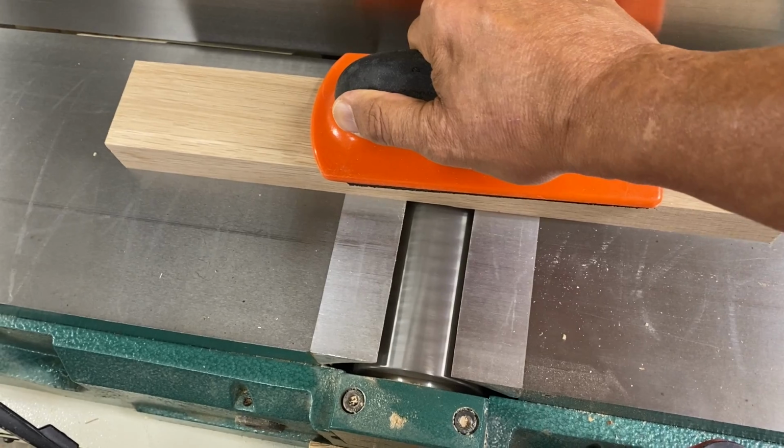I think what happens is the leading edge of the board develops a tiny bit of tear out as it passes over the cutter head, and that catches on the outfeed table. If you press down too hard on one side of the board than the other, your boards may come out looking like a trapezoid. If you ever notice that, you're probably pressing either unevenly or too hard. I know because I've done this. The aforementioned paste wax is an easy solution if you are guilty of this. If you are pressing unevenly, just be aware of it and you'll stop it.